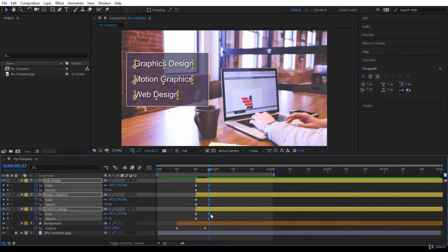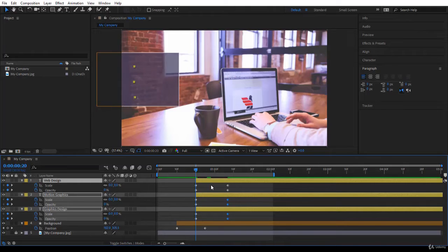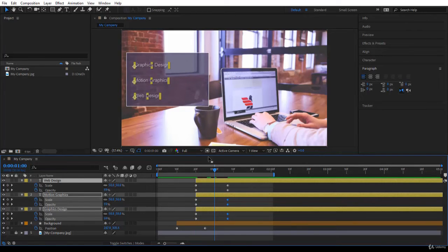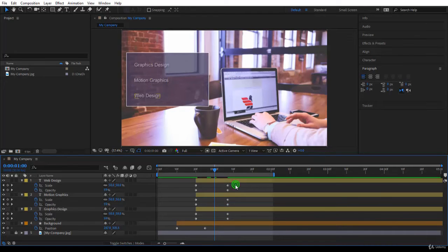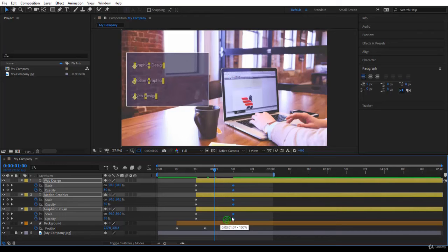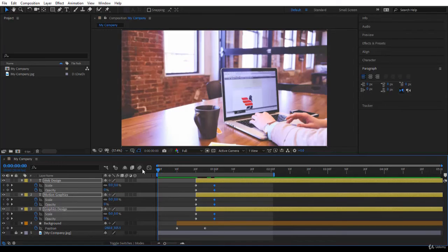You can work with timing now and decide exactly I want them at 10 frames. Let's go to the in point. I press I and I want to go plus 10 frames. So I will write plus 10 frames, as simple as this, and the time indicator will jump plus 10 frames from where it was. Then let's select the keyframes again and go nearby the timeline indicator, press shift, it will snap. Let's look at our animation now.